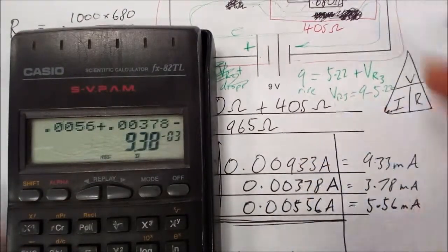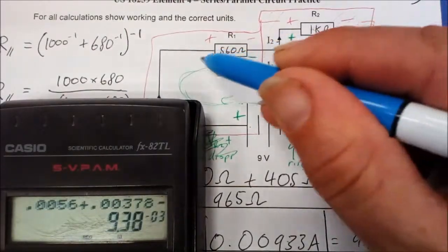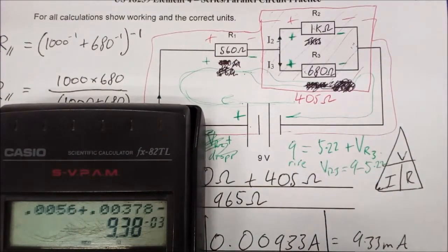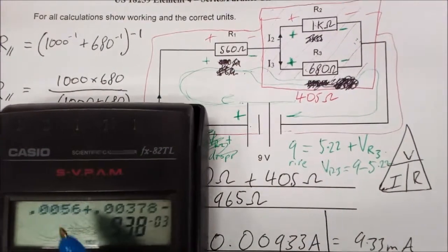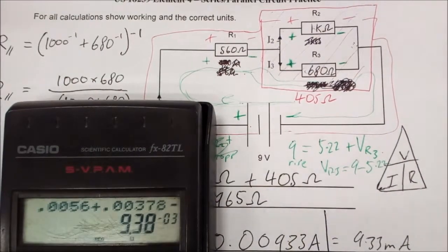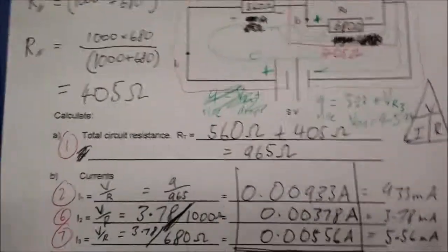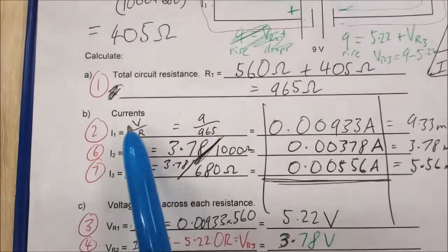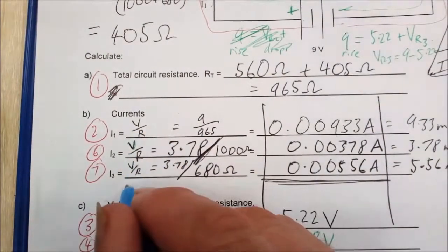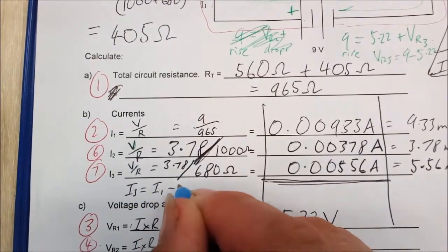These two currents, I2 plus I3, should equal I1, and there's I1 there. In fact, I left out a detail; it would have come out with a good answer had I plugged that in better. Okay, so we have solved everything. I should have said you could also subtract I2 from I1 to get I3. So you could have gone I3 equals I1 minus I2.